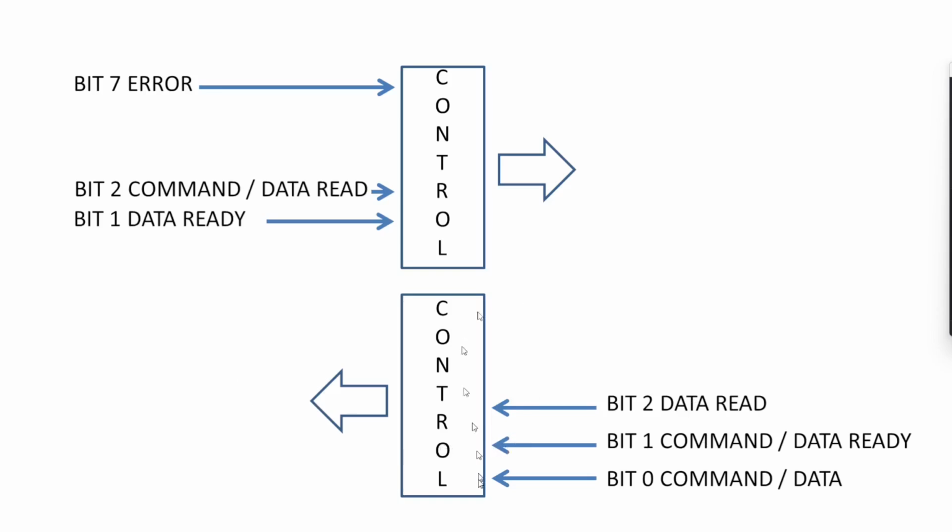If we put them all on at once, this line here could go high before the others do, and thus it could misread it. So where you've got this command bit here, this bit might get read before this bit, just purely because the pulse coming in isn't a straight line. They've got a slope to them. And this is an asynchronous interface, so you're just waiting for the pulses, like RS232, really.